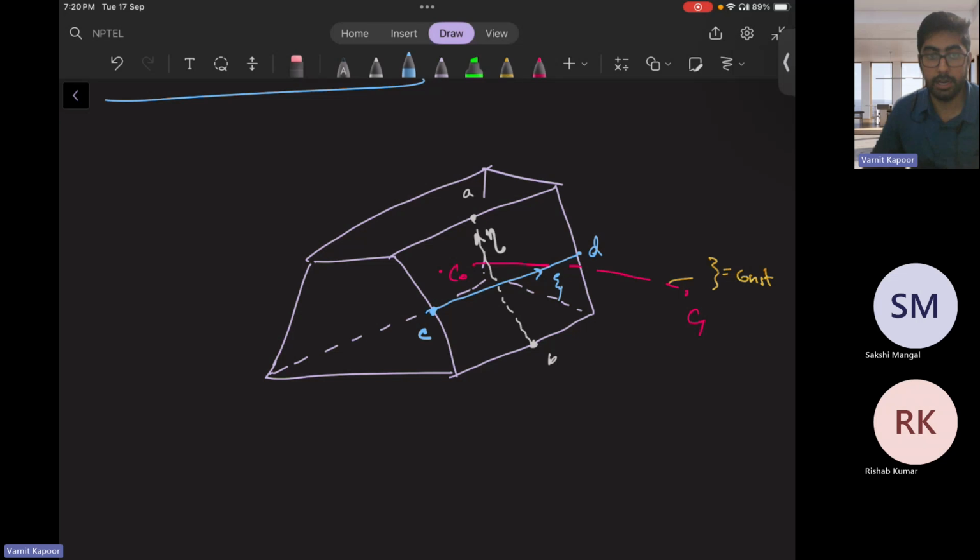So in total, we have three gradient terms. If we boil it down to a three-dimensional Cartesian mesh, we used to have ∂φ/∂x, ∂φ/∂y, ∂φ/∂z. But there, A_x is only pointing in the i direction, and ∂φ/∂y and ∂φ/∂z would come to zero at that time. But here it is not.